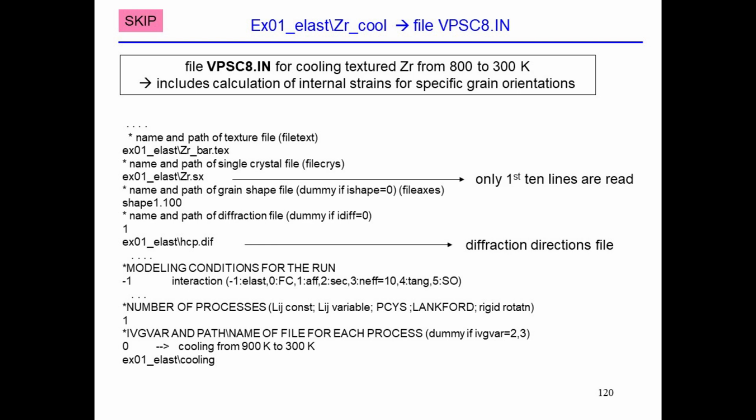And so in this case, as you can see, all of the strain components, except for the rotation of the whole sample, which has to be kept fixed, you don't impose any of the strain components. They are going to be a consequence, and this is strain, not strain rate. They are going to be a consequence of the heating, and you do need to put something here as a guess to get started. But you enforce all the stress components, and you say that all the stress components are zero, because essentially you put this in your furnace, there are no stresses.